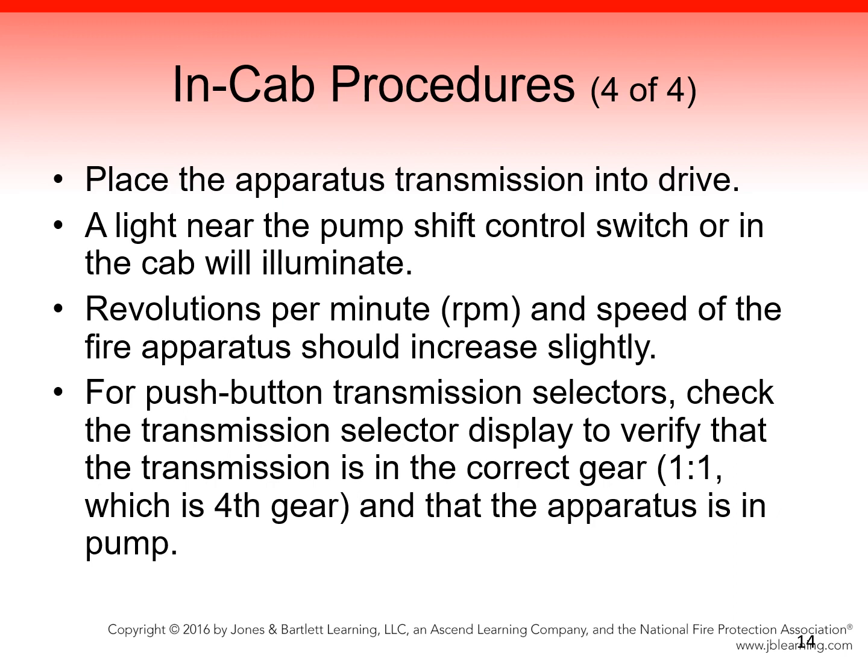In conjunction with this OK to pump light, you should hear the revolutions per minute (RPM) of the fire apparatus increase slightly, and depending on the apparatus, you may see a reading of 10 to 15 miles per hour, 16 to 24 km per hour on the speedometer. Not all apparatus will show a speed increase on the speedometer, however, as some speedometers are disabled when the apparatus is in pump.